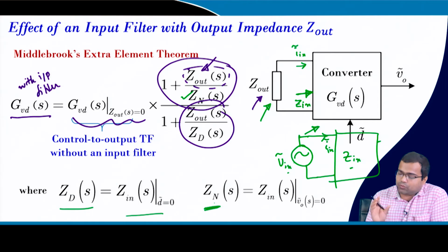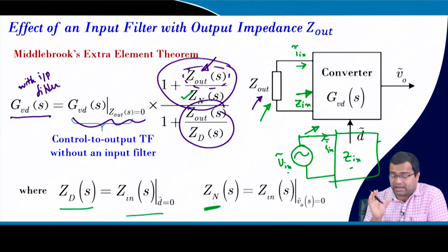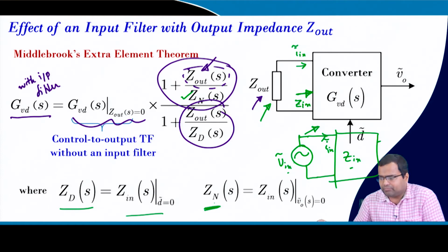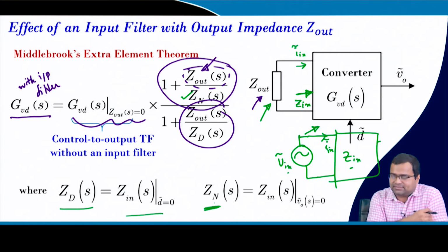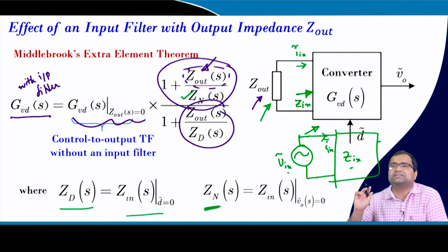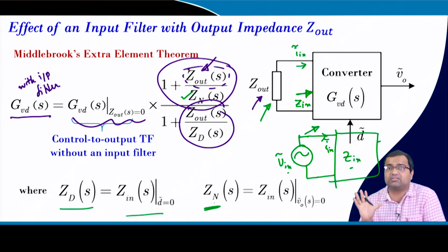That means we need to have a suitable control mechanism by which we can actually nullify this effect. And how can we do that? We can do that even using feed forward control, that we have discussed, right. So, we need to place a suitable control logic to do that. We can use a simple voltage mode control with an input voltage feed forward, and if we do that, then you can reject the disturbance in the output side. That is our objective.